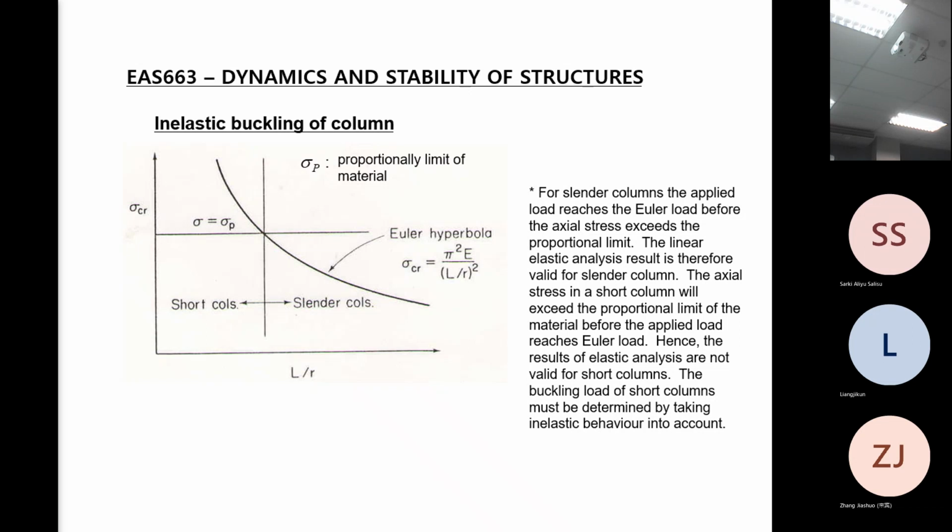But in an actual column, if it is short, then the load that we apply will cause stress more than the yield stress before it buckles. So the column will behave inelastically. And to understand those columns, we need inelastic theory. Okay? We will not have time to cover that, but in the material that I share with you, they talk about how to consider inelastic behavior in the column.